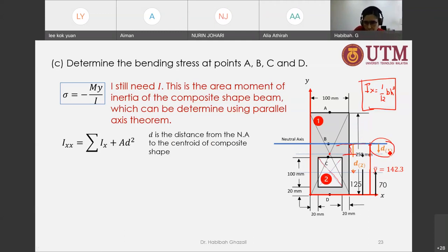It's easy. You can see that both are at the bottom of that beam, but for D, it does not really matter. Like I said, any distance from the neutral axis downward is negative, and upward from the neutral axis is positive. But in this case it does not matter, because we are going to square them anyway, and squaring a negative number gives a positive as well.